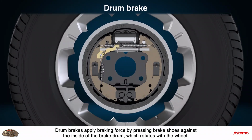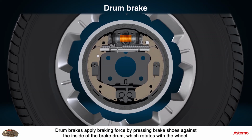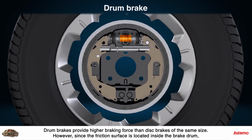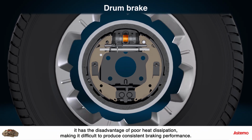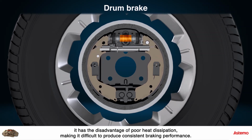Drum brakes apply braking force by pressing brake shoes against the inside of the brake drum, which rotates with the wheel. Drum brakes provide higher braking force than disc brakes of the same size. However, since the friction surface is located inside the brake drum, it has the disadvantage of poor heat dissipation, making it difficult to produce consistent braking performance.